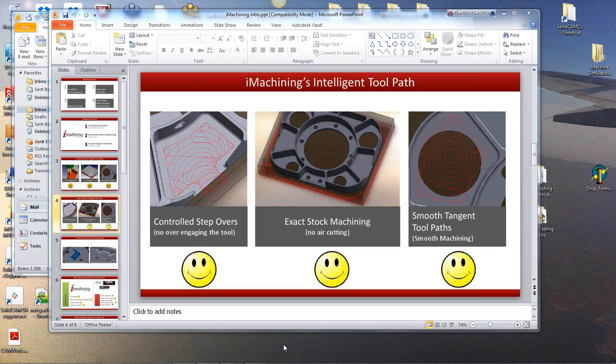And this webinar is going to be covering the 3D flavour of iMachining. Earlier on we did the 2D version, if any of you were also attending that webinar. And in that webinar we learned all about how iMachining uses intelligent control stepovers and morphing spirals, etc., to create its unique toolpath. In this webinar we will be seeing how we also can use the same strategy in a 3D machining environment, and also a separation of various areas and what have you, to create less air cutting and a more streamlined and efficient toolpath.